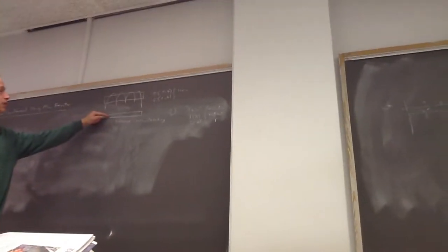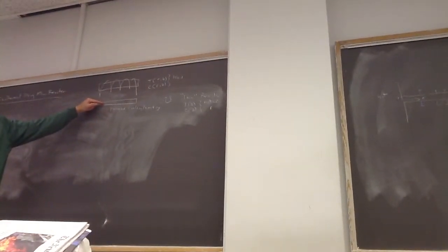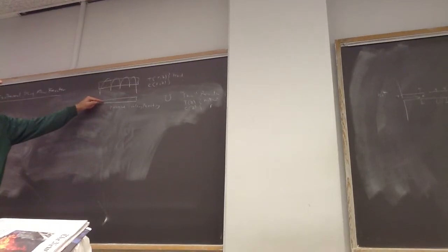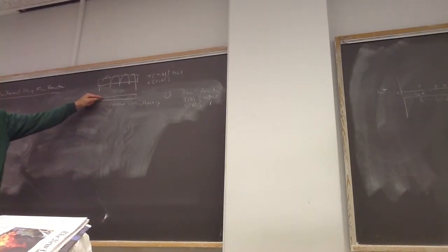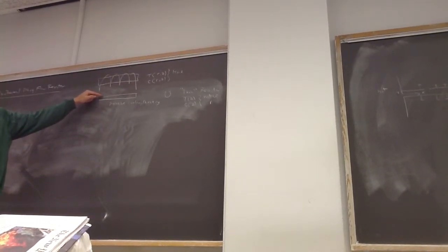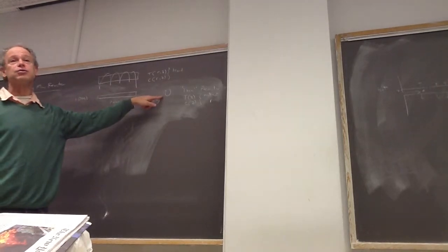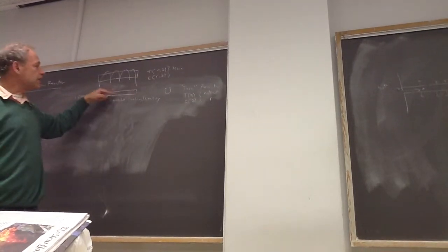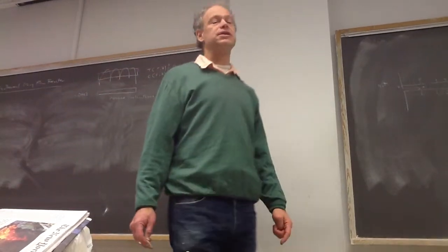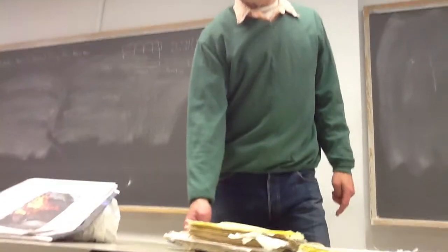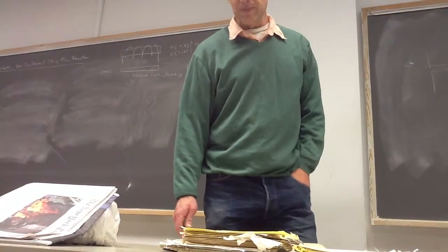Similarly here, it's the same idea: as long as the rate at which the heat, which is produced by reaction, transfers from the center to the edge, so it's a dimensionless quantity that's going to involve the radius of the tube, is fast compared with the rate at which I have cooling, here in terms of U, then I can ignore the R dependence. I'm not going to make that precise here. I'll let you do that. Now I'm just going to assume that.